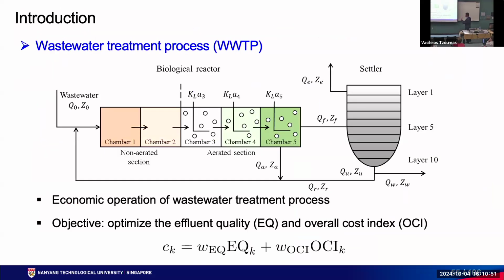For example, we use a wastewater treatment plant for illustration. Actually, there's no set point to track. When we perform set point tracking, we solve a static optimization problem. But that optimization problem is not valid because we have constantly fluctuating disturbances from the upstream user. There's no optimal set point for this plant, and it doesn't make sense.